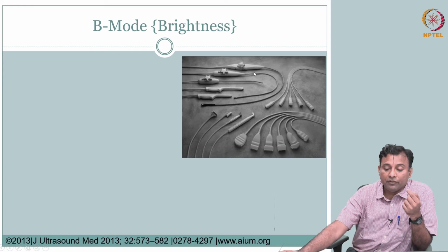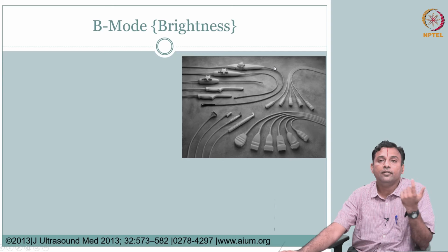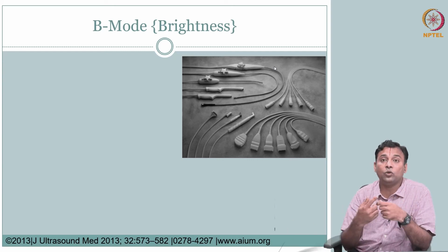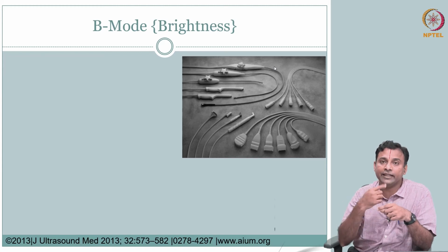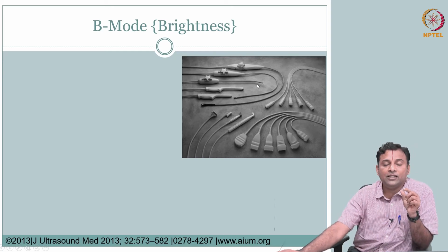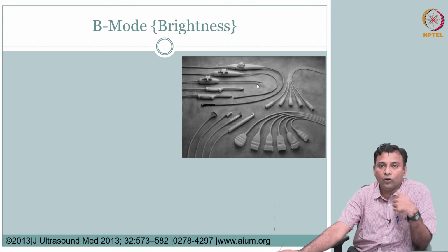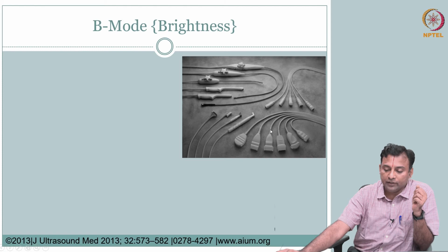Because, for example, in transesophageal imaging, you have to send the transducer through the opening. In intravascular imaging, you want to send it through the blood vessel so that you can go inside and see. So, you have to have a transducer size that is small enough to go into the body. So, you have several different sizes and shapes depending on the application, single element with mechanical articulation, right, two different types of probes that you see here.